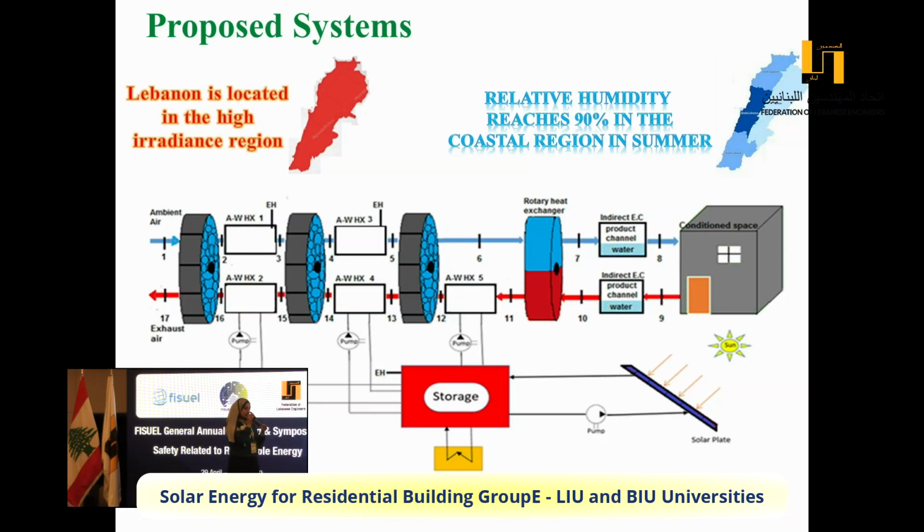Can you imagine the silica gel as a ball? In the first stream, this ball will be filled with water, and it is now in the downstream. Once the temperature is 70 degrees, this desiccant will return to its initial size. So this cycle will be repeated.